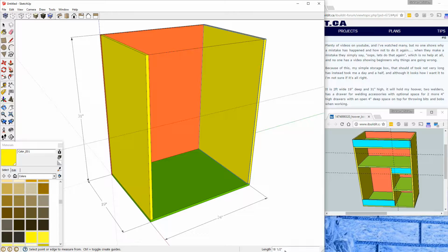The same principle applies, of course. You could put in any dimensions here. And then what I'm going to do is just again use the measuring tool and just put a measure on there for that guide that I've just put on, just to make sure that it's the right height. So it's a 4-inch gap that I've created.